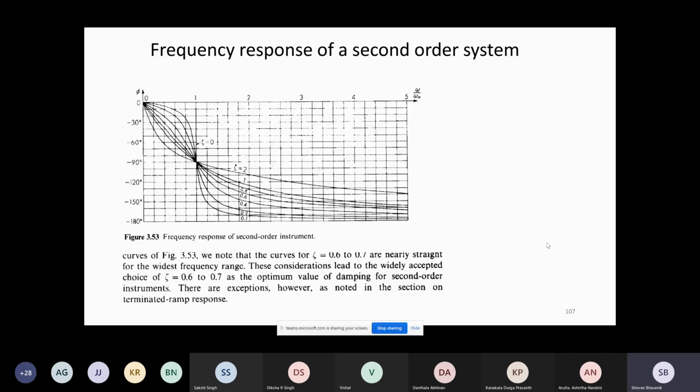In fact, in our control and instrumentation lab, we have an experiment where we generally give you a black box which has some circuit inside. You cannot see that; you can only see the input terminal and the output terminals, and from there you need to determine the transfer function of the system inside the box. So to start with, you need to know how to draw a Bode plot. There are two approaches.